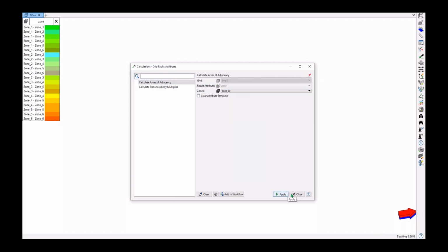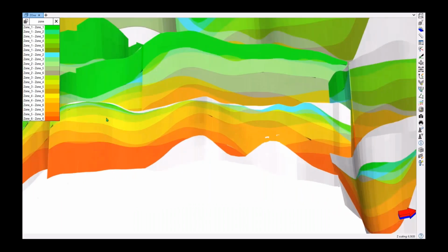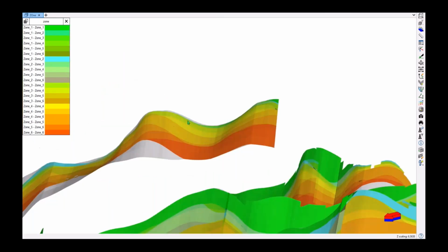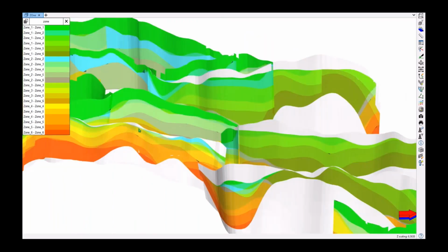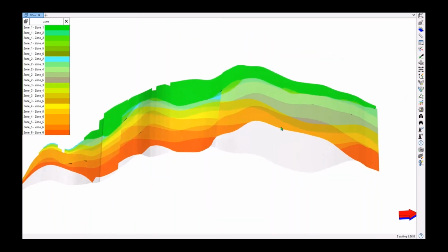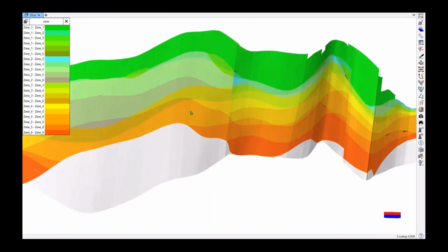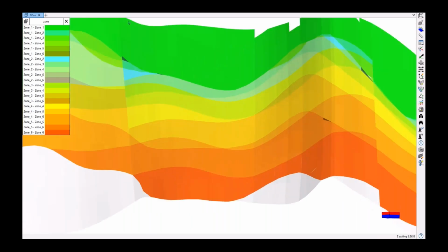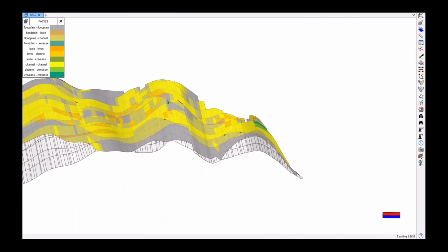Because we've created V-shale and permeability, I'm going to touch on some fault analysis tools. Here we're calculating areas of adjacency, these Allan diagrams, which allow you to cross-check where your zones are touching each side of your fault. We can do this for any discrete property. If it's zone or facies, we can see where zone 4 is touching zone 3, where zone 5 is touching zone 1, and we can really see the displacement across each of our faults and which of our zones and layers are speaking to each other. As I said, we can do this for any discrete property.